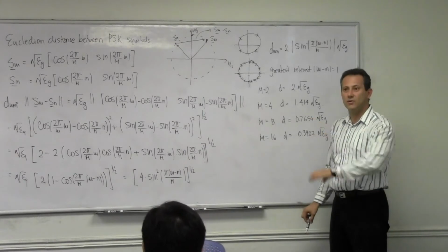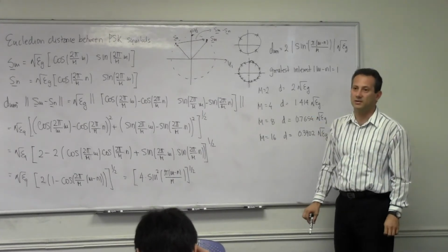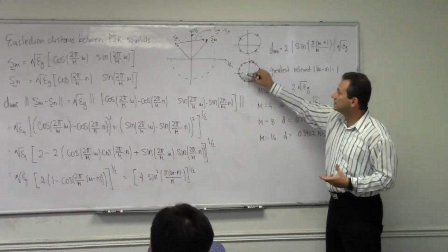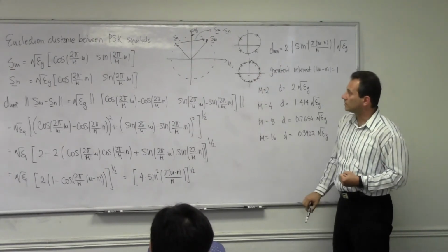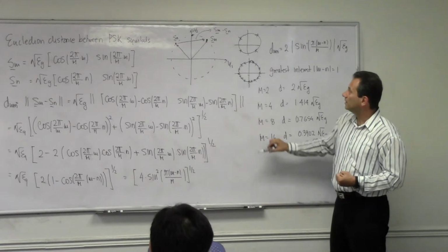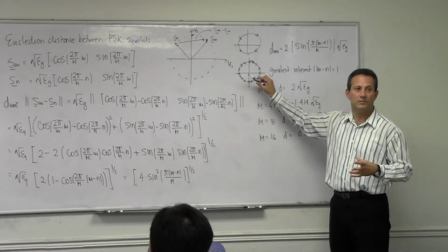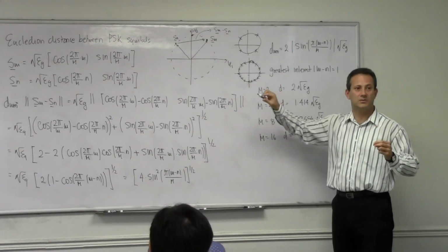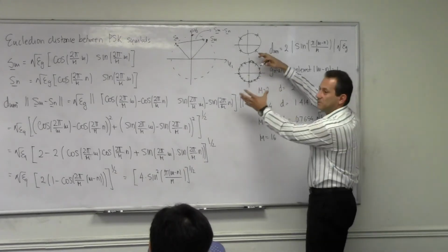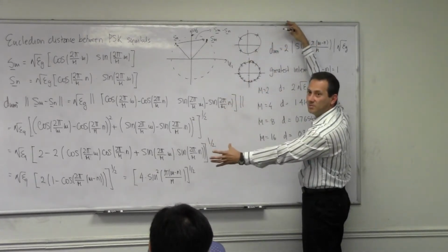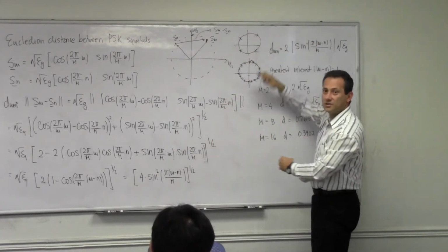We have some ways of coding that in a smart way, but you can see that as you keep on increasing the number of constellation symbols, to preserve the same probability of error, what is it that I need to do? Or to preserve the same distance between them? I need to pump this circle, right? So if I put more points, the circle needs to be bigger, so my energy needs to grow.